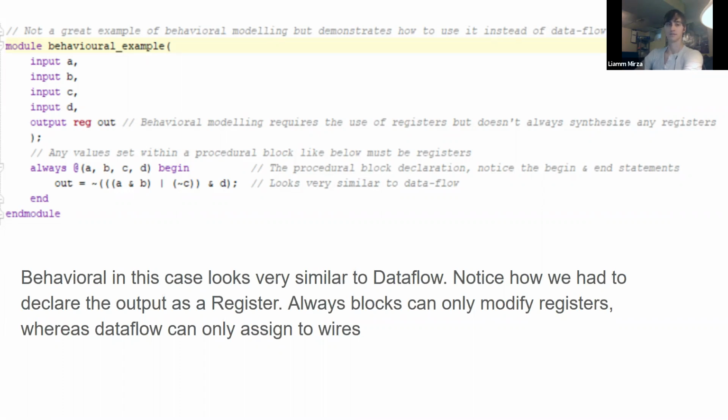Though you can't really control it if it's an asterisk, like if you add something there down the line. In the case that you actually did want to latch, the asterisk doesn't work. You can't control it. Sometimes you want latches, sometimes you don't. There's a whole debate on whether or not latches should ever exist, but there are some good reasons to have them every now and then.